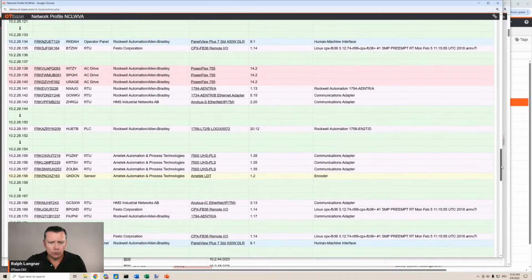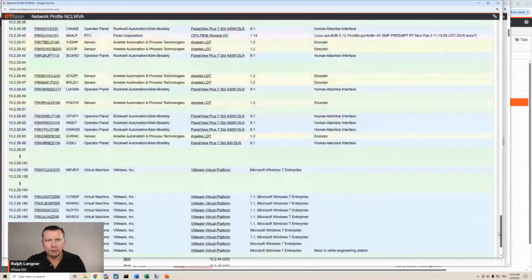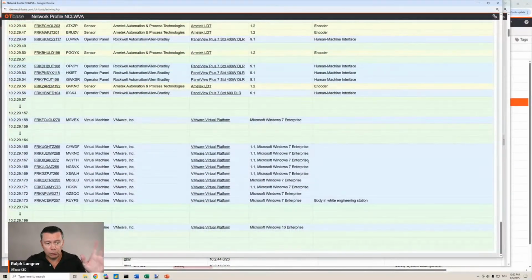So this is what you would expect to find in a properly segregated network architecture. You have a bunch of PCs in there. You may even have actuators in there. Because this is all oriented about functionality. If one of these devices crashes, goes down, well, the others won't be able to continue operations anyway. So this is microsegmentation, and what you should not do when you think about Purdue, don't do that horizontal layering. It's, I would say, a really bad abuse of Purdue.